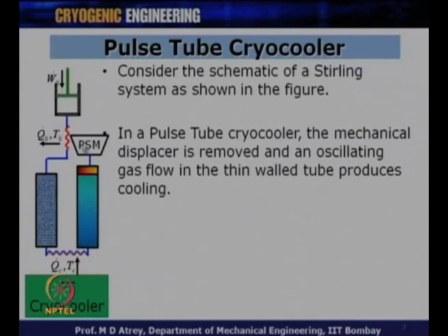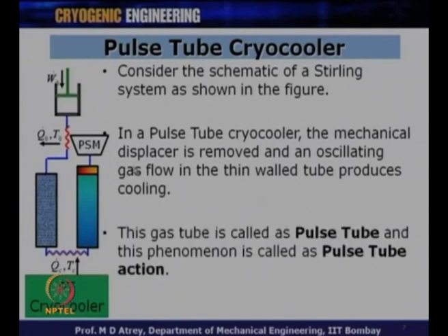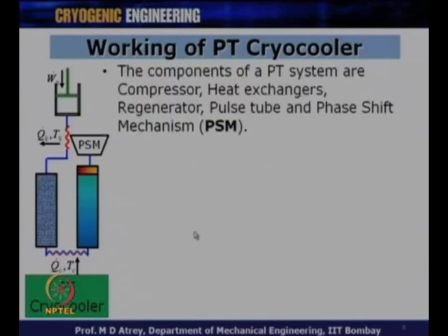Now, there is something called PSM, which is what I will talk about. This gas tube is called the pulse tube, and this phenomenon is called pulse tube action. The components of a pulse tube system therefore are a compressor, heat exchanger, regenerator, pulse tube, and phase shift mechanism.